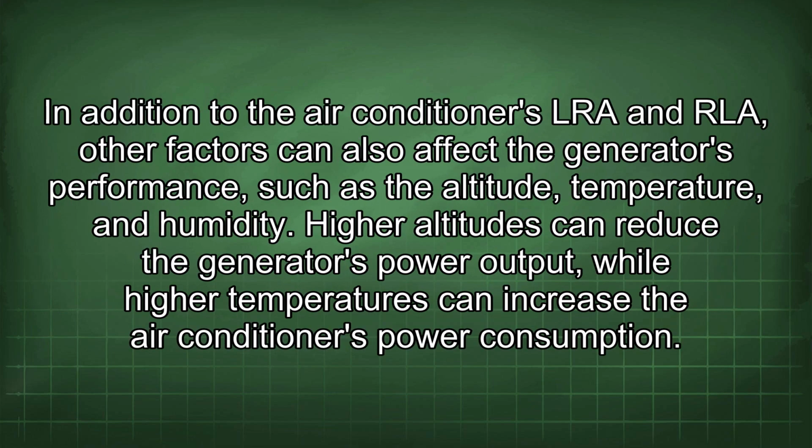In addition to the air conditioner's LRA and RLA, other factors can also affect the generator's performance, such as the altitude, temperature, and humidity. Higher altitudes can reduce the generator's power output, while high temperatures can increase the air conditioner's power consumption.